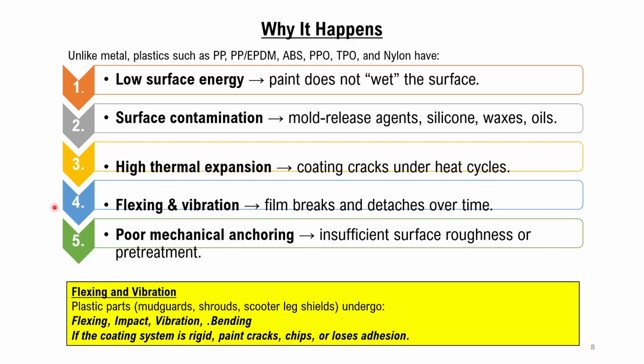Number four, flexing and vibration: the film breaks and detaches over time. Number five, poor mechanical anchoring, that is, insufficient surface roughness or treatment.